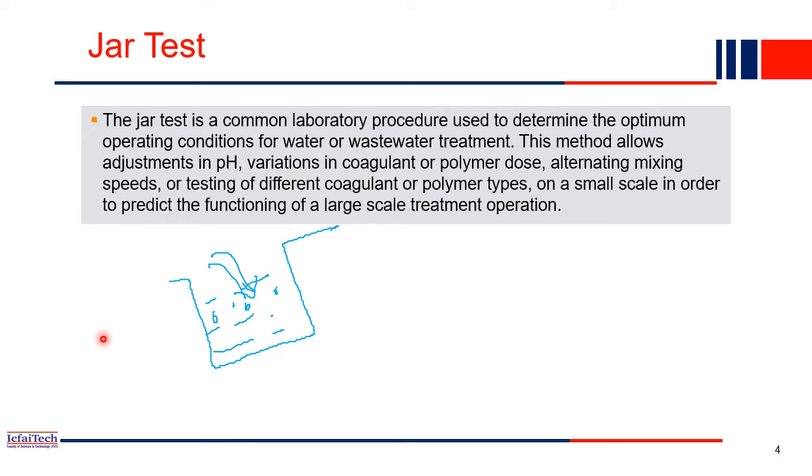So in a water treatment plant, you understand now water is coming from the addition tank to the primary sedimentation tank. From the primary sedimentation tank, it comes to the secondary sedimentation tank, where we add extra chemicals, that is coagulants. Now, how much coagulant will you add? That is the next question. How much coagulant you add is determined based on the jar test.